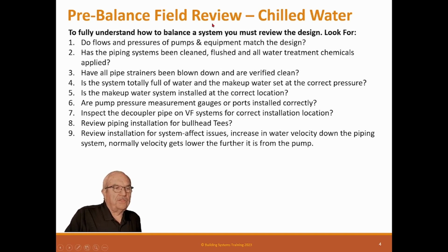Review the installation for system effect issues. Increase in water velocity down the pipe, same thing we did for the design. We want to make sure they haven't done something, because remember, the drawings are somewhat dogmatic in nature, and a contractor may not actually install the system exactly like it looks on the drawing. There's nothing wrong with that. It just makes sure they don't have any issues that are not going to allow the system to be functional.